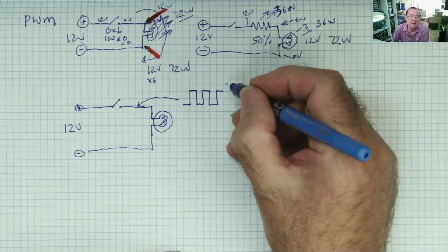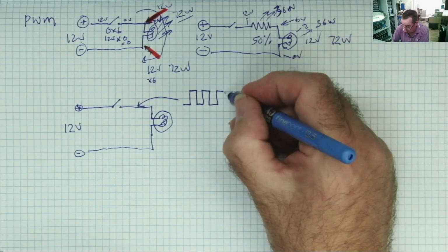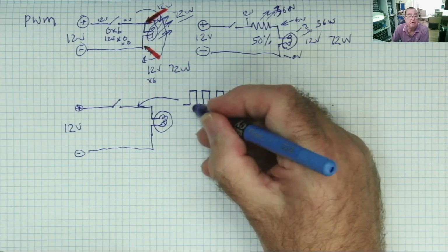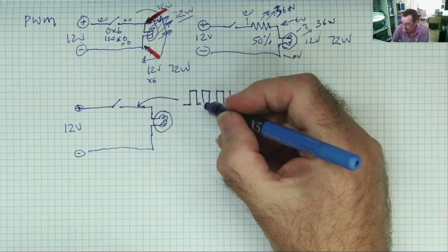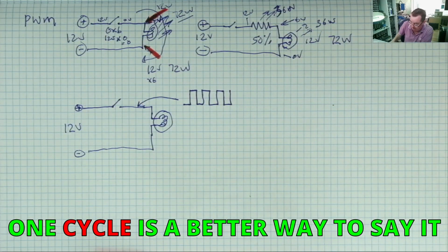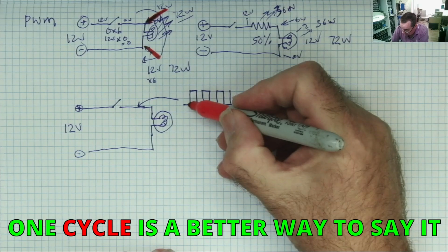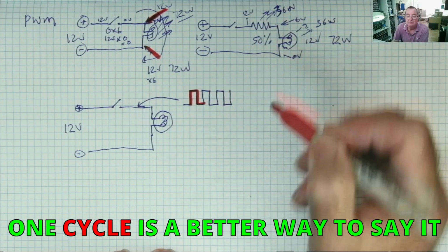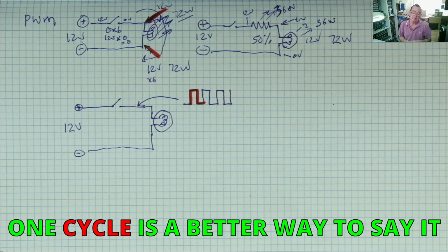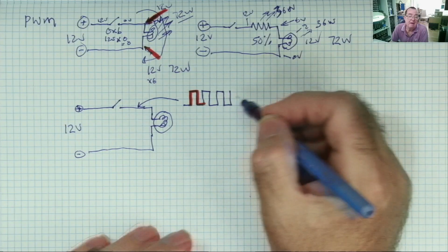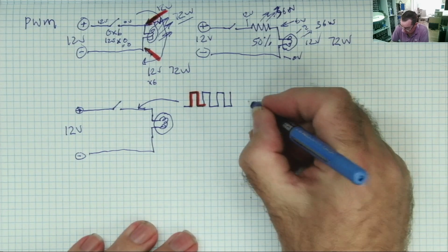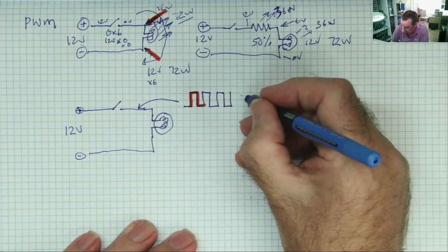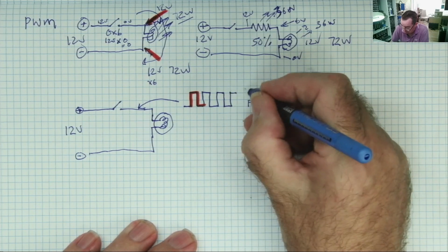This is a square wave, going between 0 and 12. The duration of the wave, and this is one wave, from the rising point here to the falling and back to there, that classes as one wave, and then it repeats. The rate at which it repeats is called the frequency. While we're on this, the height of the wave, how high it is, is called the amplitude.